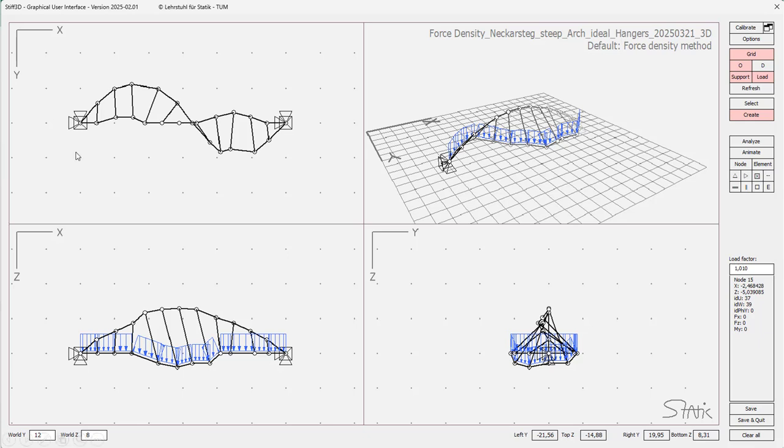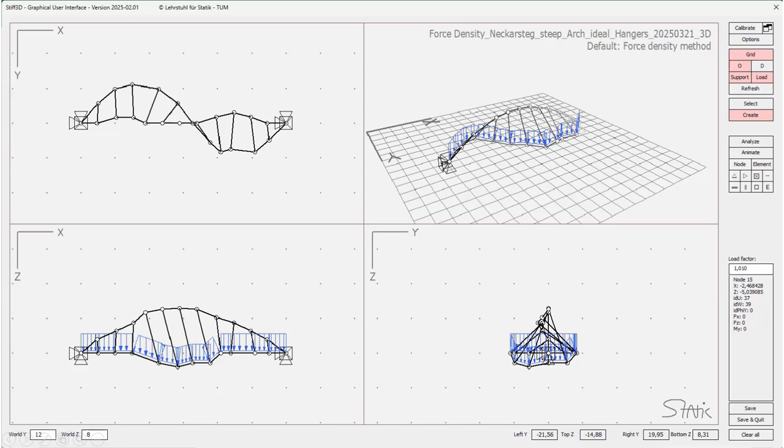which is aligned with the benchmark from Schleich, Bergermann and Partner, where we have this pedestrian bridge with an arch and a curved deck in a curved line. And I will now show you the success of all our techniques, together with self-weight of the deck, together with controlled positions of these nodes. You would like to have a horizontal deck, also controlling the apex of this arch, and eventually also the length of the deck element to be constrained. Let's take a look at how this works.